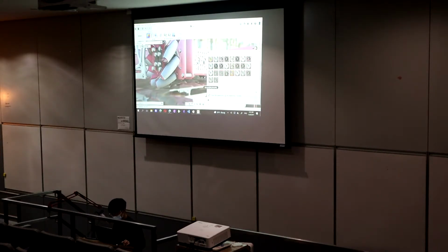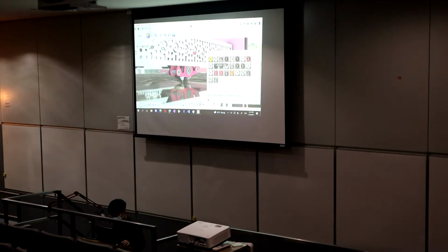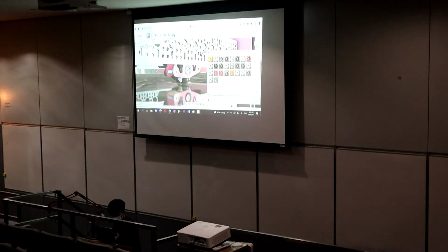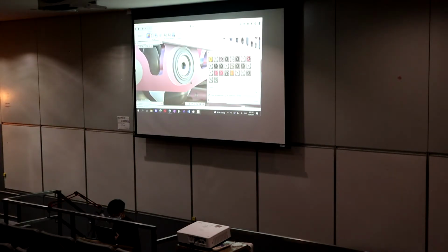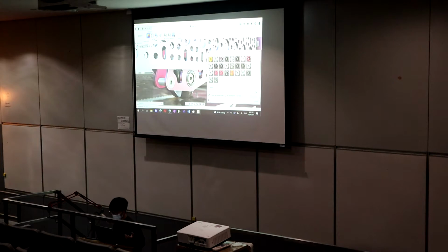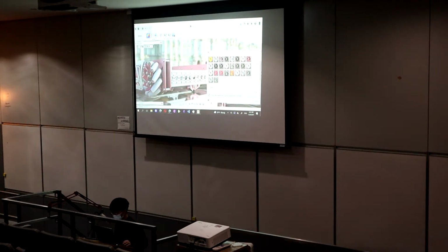And there's also a few other things that we can do. Normally when we buy motors in FTC, they come with a sticker on them, right? The sticker shows what gear ratio or what speed they're at. What we can actually do is insert these kinds of stickers. They're called decals. We can go over to here and insert a decal. I'm going to insert this from my computer. And let's go build a sticker decal. And I'm just going to quickly resize everything.